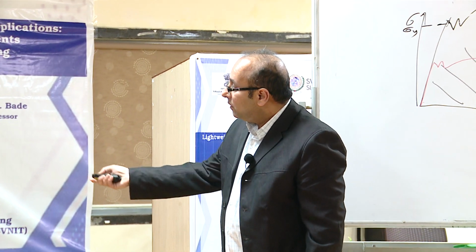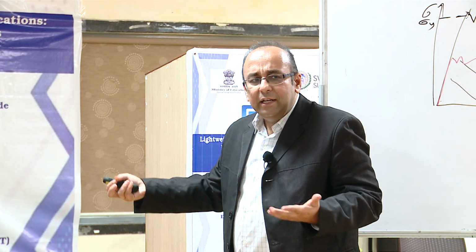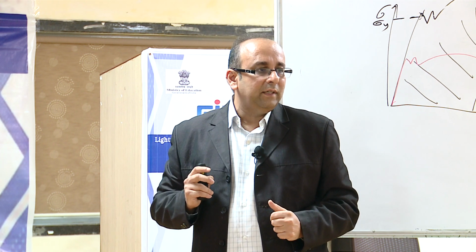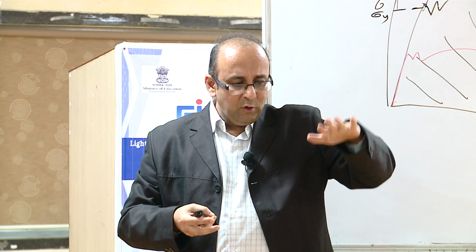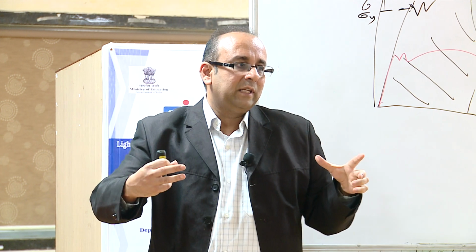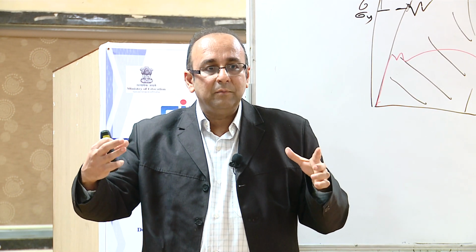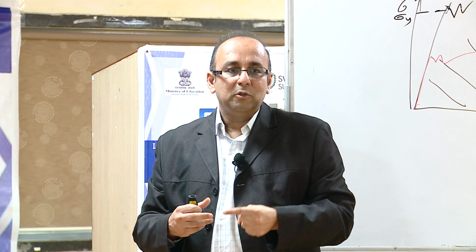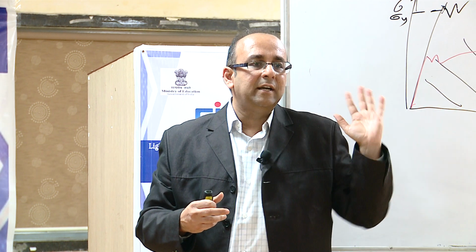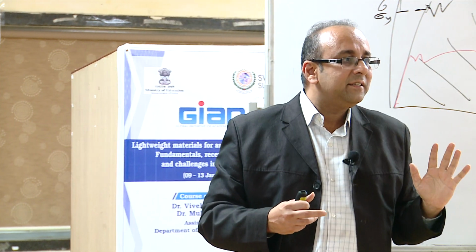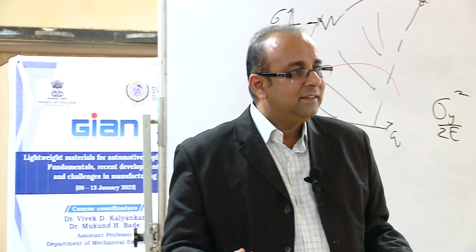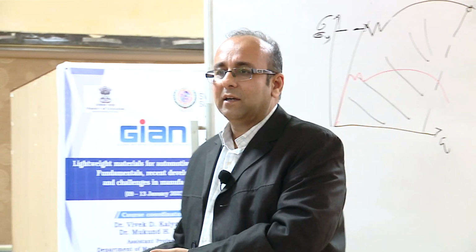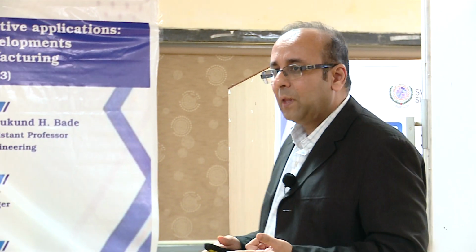The other way is, why heat this part? Why heat it up to 950? Why give that energy? Why not heat only the required part? So how do you do it? When you have this part, you put a big mass on it, ceramic or any additional mass, so that the convection heat is not touching that area of the part. So that area of the part may be just 200 to 300 degrees centigrade. It will not even reach austenite. If it does not reach austenite, it cannot become martensite. So the second way is, don't heat that part to the required temperature.